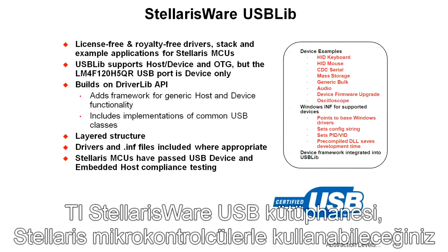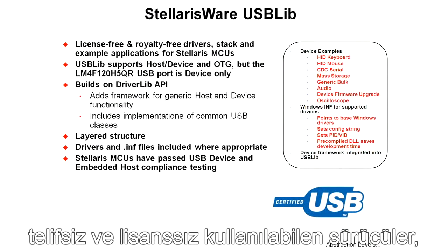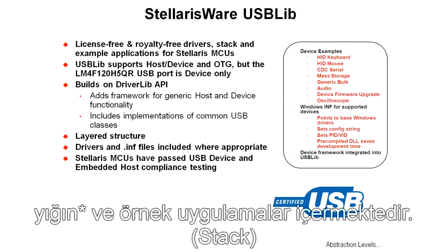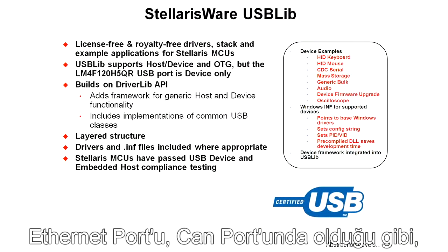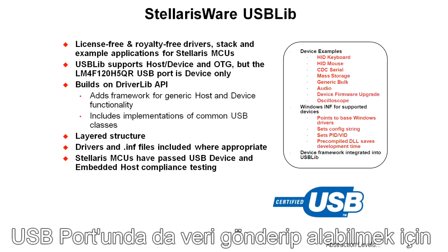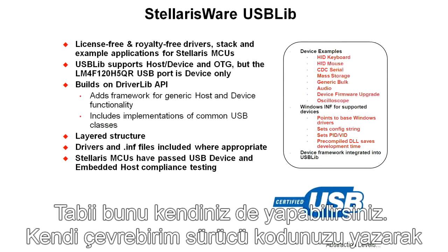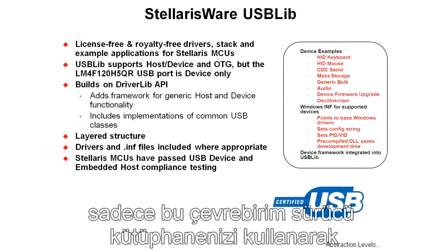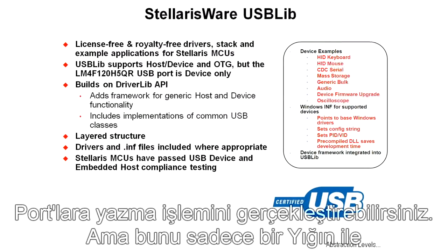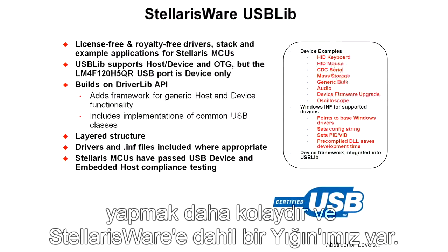TI's StellarisWare USB library is a license-free and royalty-free set of drivers, stack, and example applications for Stellaris microcontrollers. Now, like an Ethernet port, like a CAN port, there is a stack that you interact with to send information back and forth across the USB port. Of course, you can do it yourself. You can write your own peripheral driver code and write through the ports using just the peripheral driver library, but it's a lot easier just to talk to the stack, and we have a stack as part of StellarisWare.